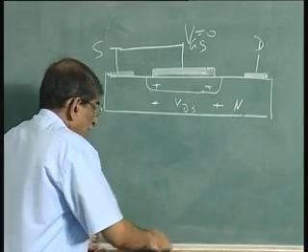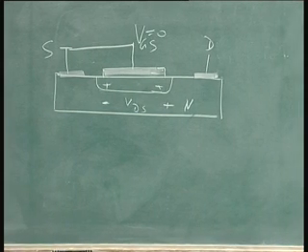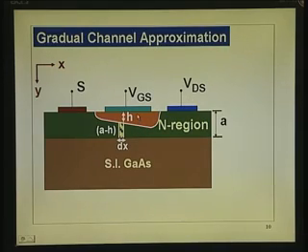So, as a result of that, that is what I plotted here. The depletion layer here becomes wider. Here it is VBI if VDS is 0; here it is VBI plus VDS. At any point here, it is VBI plus V of x. I hope that point is clear enough. It just adds on to the depletion layer potential. Across the depletion layer, it is addition.